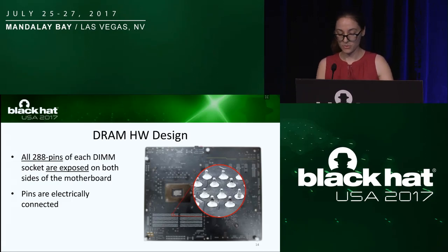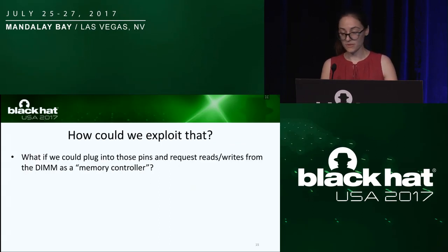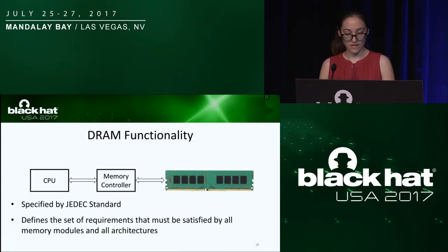And I would also like to point out this is a standard OEM design. This is not something that is specific to that board. But the question that we raised is how could we exploit that in a little bit more sophisticated way? And specifically, what if we could plug into those pins and just request normal reads and writes just as the processor would, but be able to impersonate that through something else, through, say, a memory controller that the attacker has.